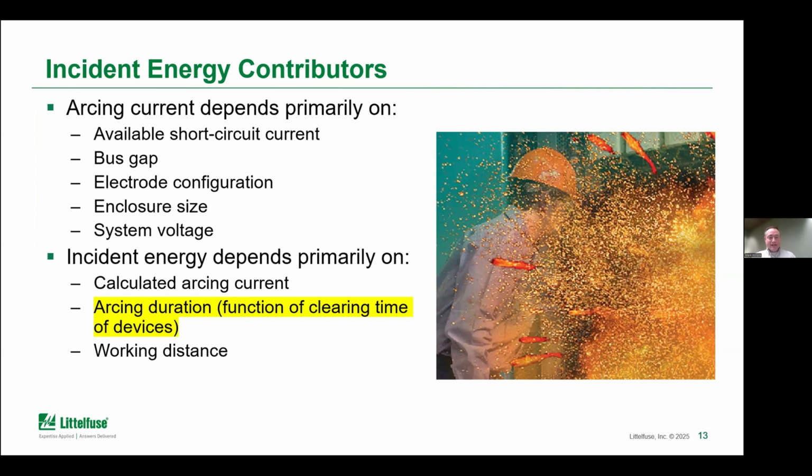Now, the arcing duration I have highlighted because that's really a focus of, if we want to reduce the arc in electrical systems, this is something that we can work on to try to make a safer system, reduce that arc energy by interrupting faster, having a faster clearing time.